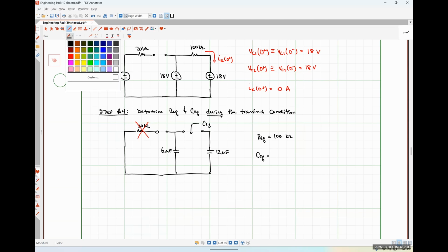The reason why I think that they're in series is if we look at our nodes, so we've got this node, and this node like so. So the purple and the blue are different nodes, which means they don't share both the top node and the bottom node. So they are not in parallel with each other. And because the 20 kilo ohm resistor isn't doing anything, I can effectively just throw that entire branch away, leaving what looks like a series connection.